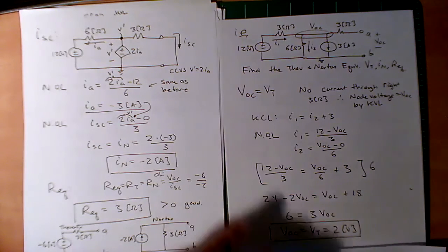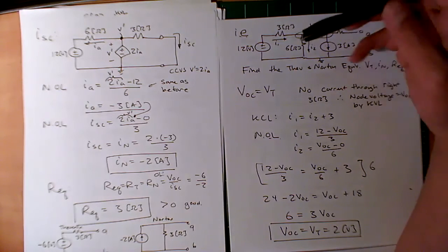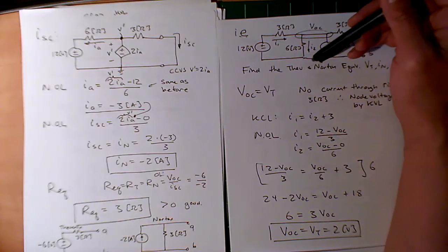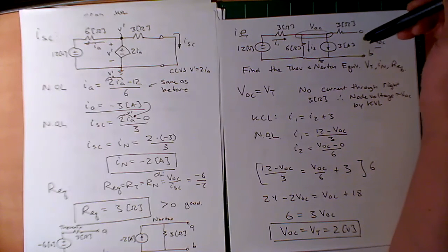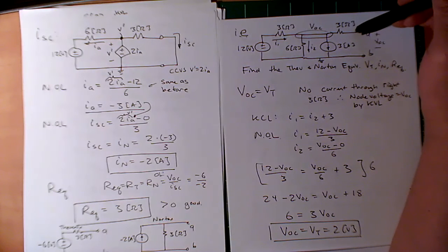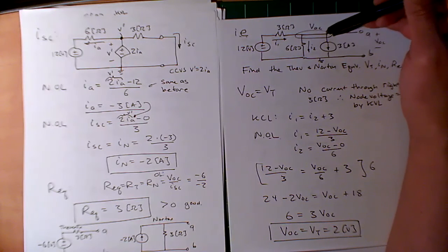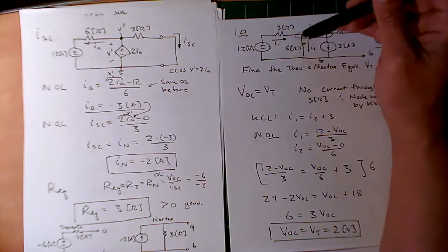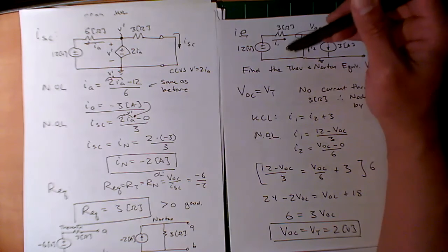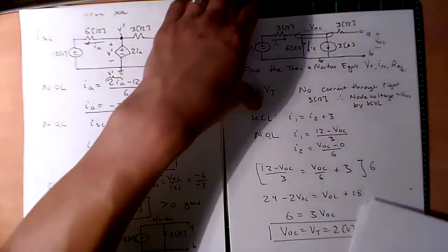All right, good. Again, does 2 volts make sense? Positive? Well, we'll see. We have a high pressure over here, with current flowing this way and going into these. It may not be as easy to see, but I could see that there might be a higher pressure over here than over here, because that 2 volts would be the same as this voltage over here. Higher pressure pushes current down, so there should be a 2 volt drop across that. I'd buy that. So let's keep going.